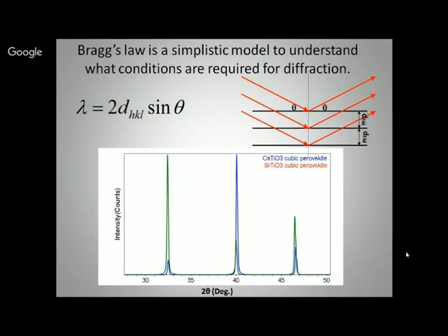But nowadays we have such a technology that we can easily judge how many peaks it has and what type of structure it has. From these peaks in the X-ray diffraction pattern, you can easily tell whether your material is cubic in nature, or hexagonal, rhombohedral, or some other structure.